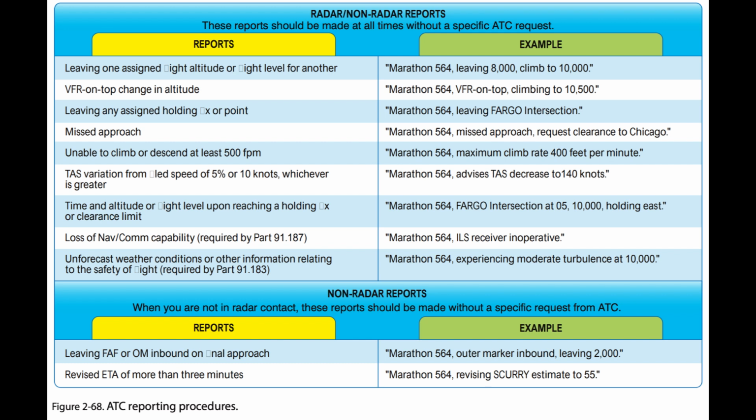6. The time and altitude or flight level upon reaching a holding fix or point to which cleared. 7. When leaving any assigned holding fix or point. Note: the report stated in subparagraph 6 may be omitted by pilots of aircraft involved in instrument training at military terminal area facilities when radar service is being provided.